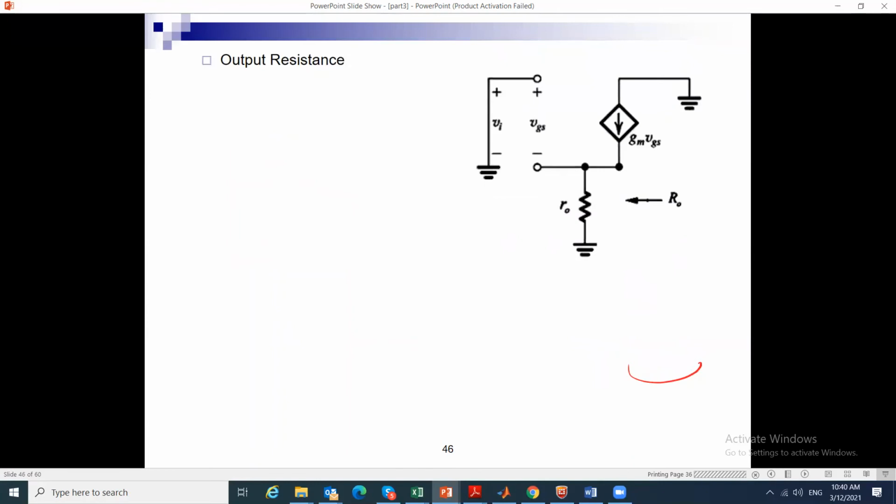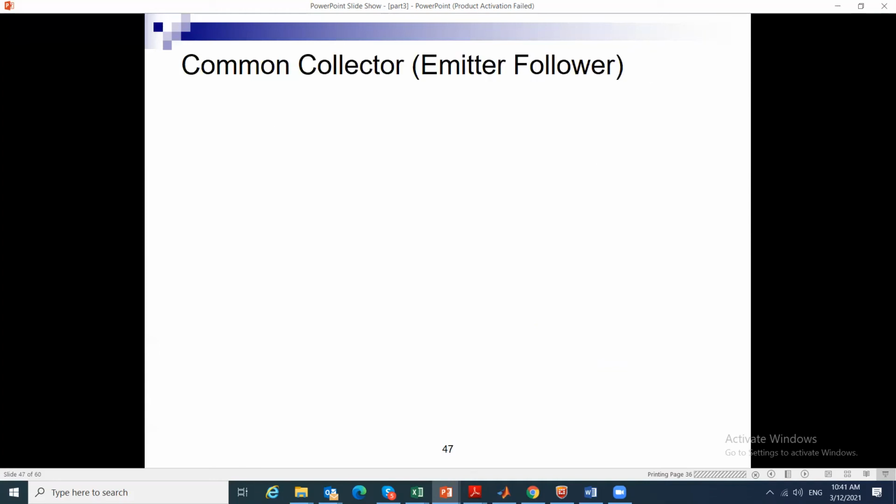And then it is telling me to derive the output resistance. It will be really RO parallel to 1 over gm, because I have RD plus RO over 1 plus gm RO, and it will be the same. If I plug this in, or if I set RD to 0 and find the equivalence of these, I will find that it is the same equation that is given here. Okay, so you can plug in whichever equation, the one from the sheet or the one from the resistor sheet, but the resistor sheet is always simplest because you look at the schematic.